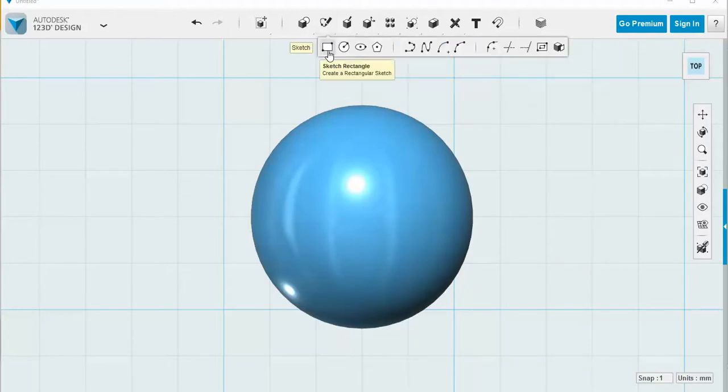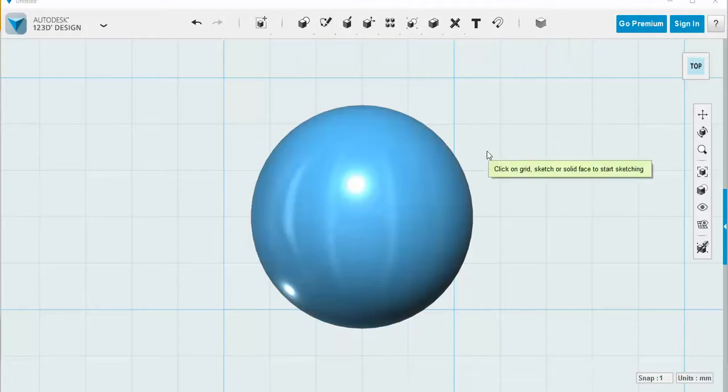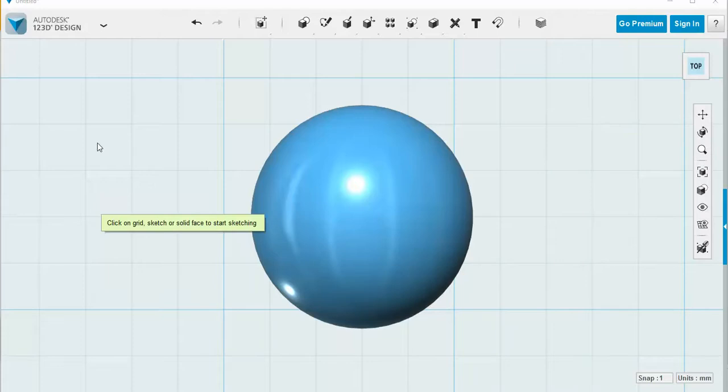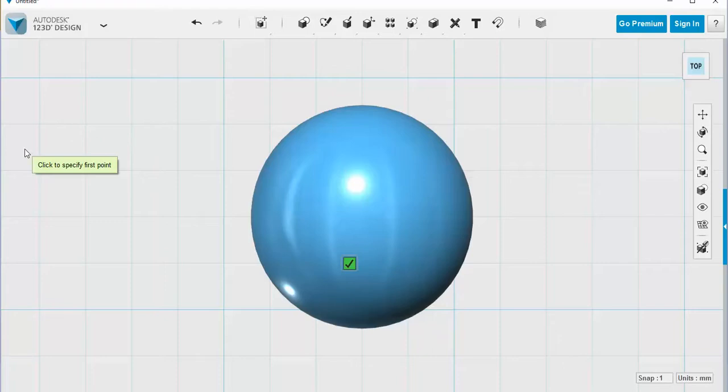When you use Polyline or any of the options in the sketch menu here, you'll need to define where you want to draw your sketch first. So before you do anything, you'll need to click on the work plane. Anywhere you can click and it'll be fine. We're just saying, hey, I want to draw it on this axis.